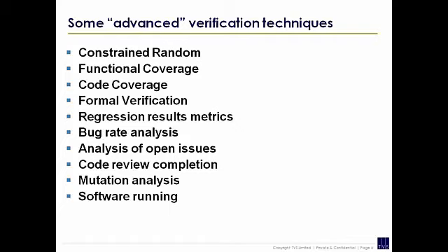So bug tracking for us not only provides a management system, it provides an analysis system where we can also look at, are we going to be able to ship on time? Is the bug rate coming down? If you move to constrained random, a constrained random bug curve, compared with a directed test bug curve, normally looks like that. So you tend to be able to ship earlier. But if you keep good statistics on bugs, you'll be able to do this type of analysis, which allows you to much more predict a completion date.